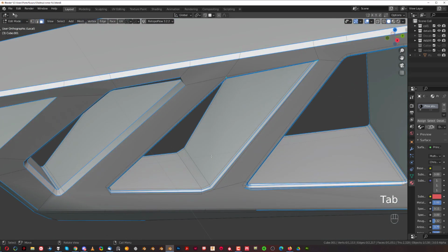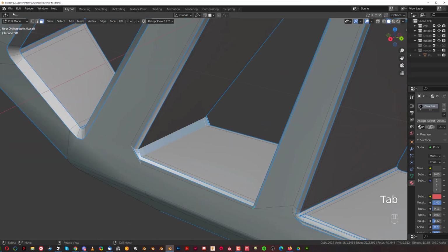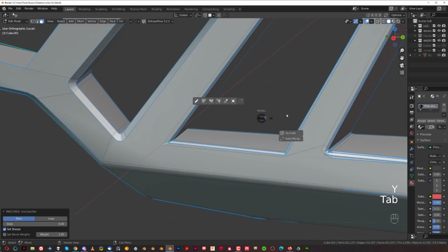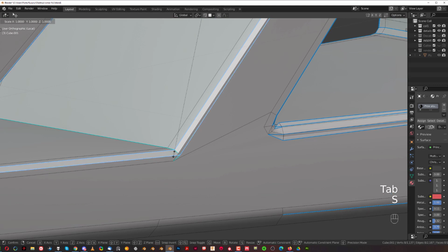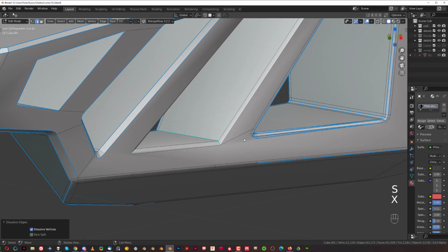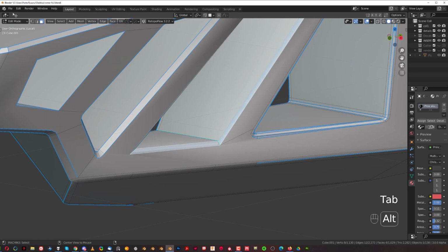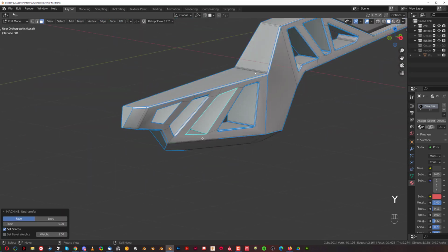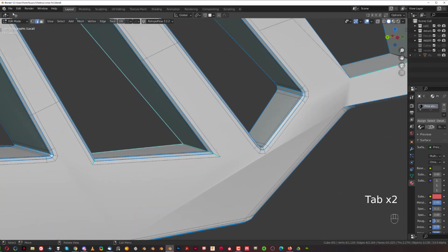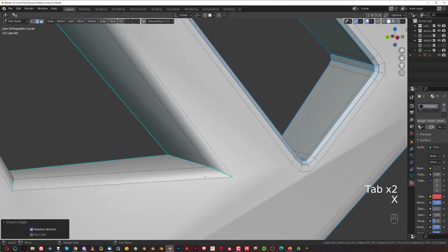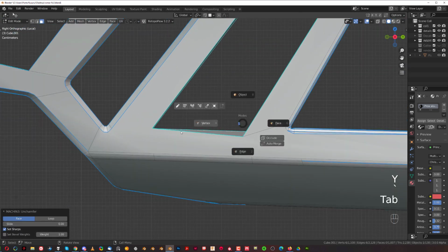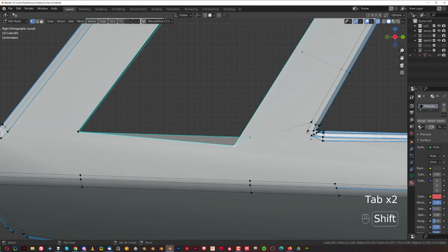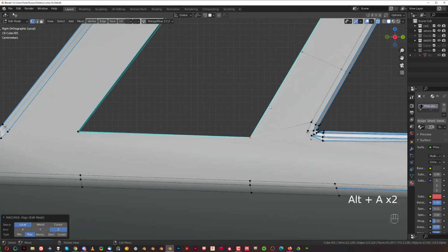And then we're going to unchamfer this one, and there's one more here. Okay, and then I'm gonna run an unchamfer on this corner, but we need to first remove these two, dissolve edges. There we go. Select this one here all around and unchamfer it, and boom, right? And then here select these two, and same here, unchamfer. Okay, and if it's not aligned, just align them, so right, top.